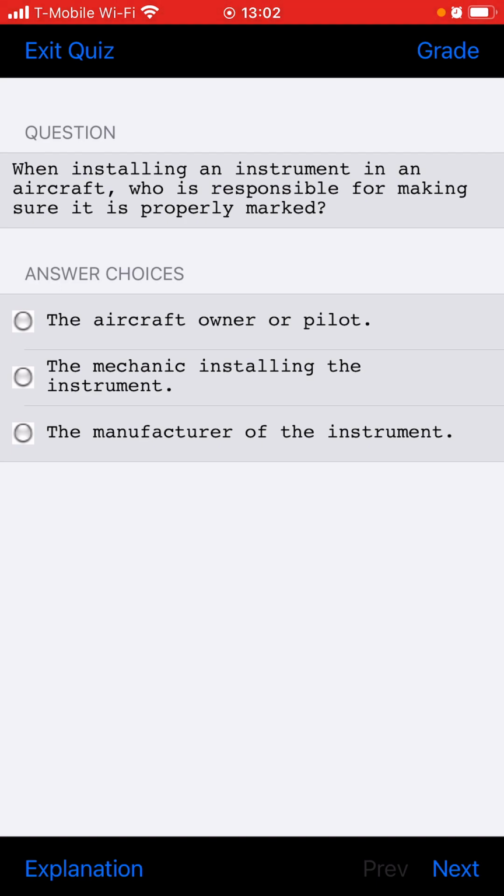Describe two methods of bleeding the brakes. One, a pressure pot can be attached to the bleeder valve and fluid forced back towards the master cylinder into the reservoir. Two, the master cylinder can be used for forcing fluid from the reservoir to the brakes.